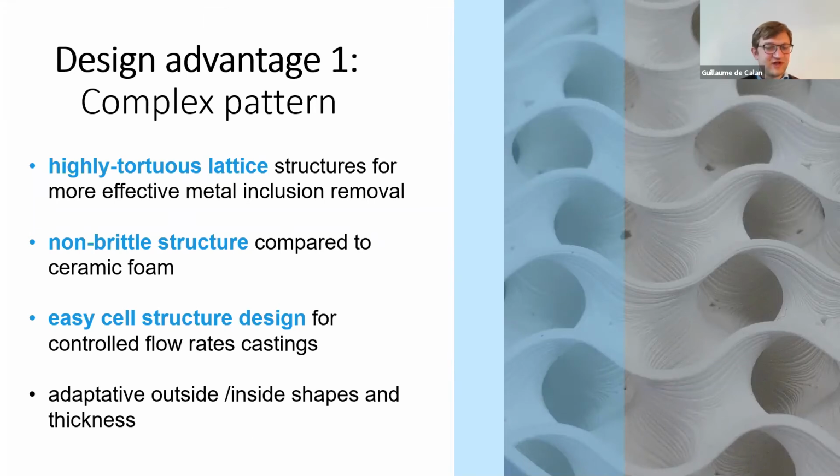We prefer direct drive printers, and we prefer printers which have, let's say, a good configuration in terms of extruder. We particularly like extruders of a brand which is called Bondtech. If you have a printer which is direct drive equipped with Bondtech, you can be absolutely certain it will work.